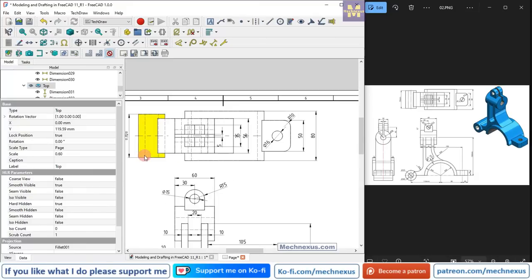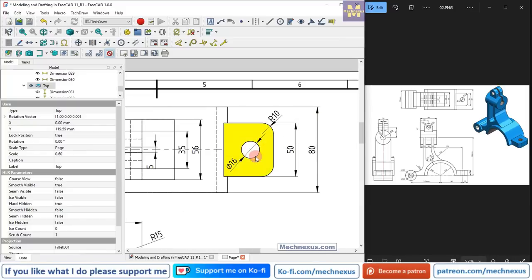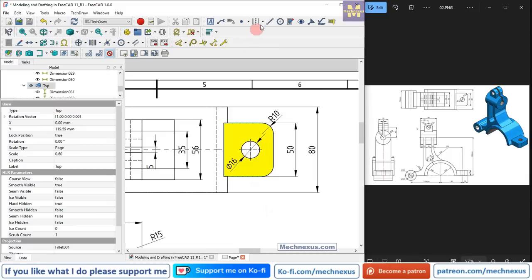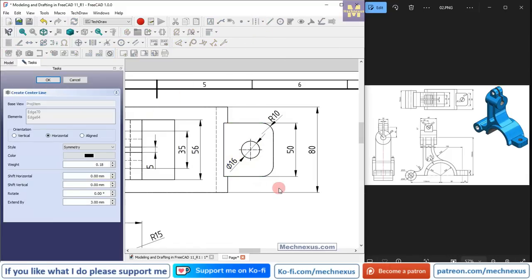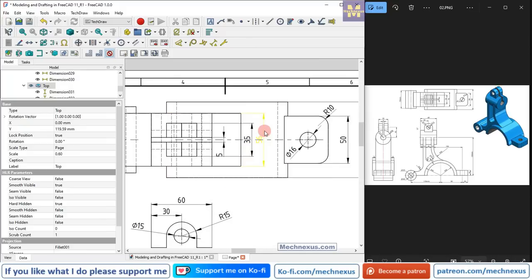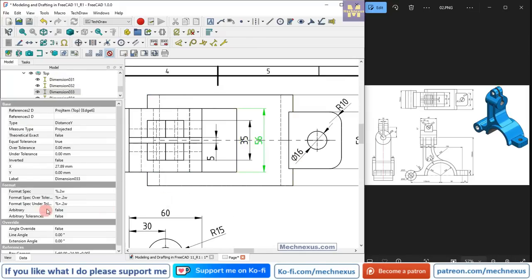Similarly, we will select this and add a center mark, and we can also add a center line so that our drawing looks good. Okay. Now for these two dimensions we can also add symmetry so that they are symmetric with the center line, and this 35 as well.